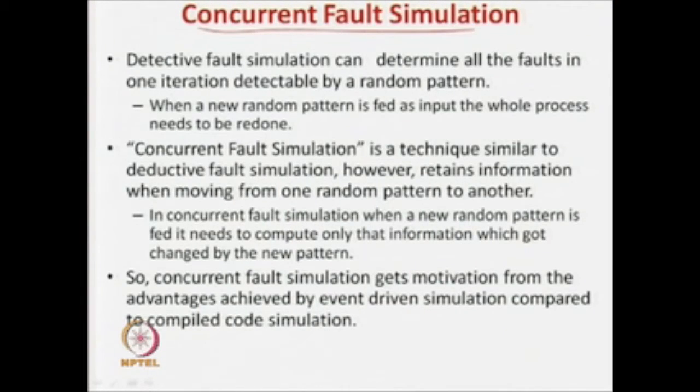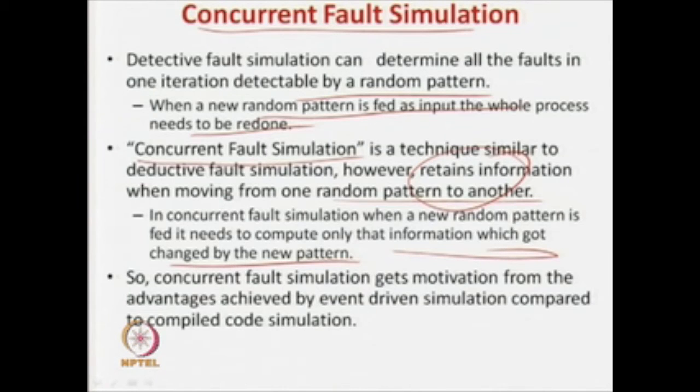That is what he is saying: deductive fault simulation, which we saw last, can determine all the faults detectable by a random pattern, fine, but when a new random pattern is applied, the whole process has to be redone. That is just like compiled code simulation, so you have to do something better. Concurrent fault simulation is a technique similar to deductive fault simulation, but you retain the information about what you have done when going for another random pattern. When a random pattern is fed, it needs to compute only that information which got changed. So concurrent fault simulation is motivated by the advantage of event driven simulation over compiled code simulation. That is the basic idea.